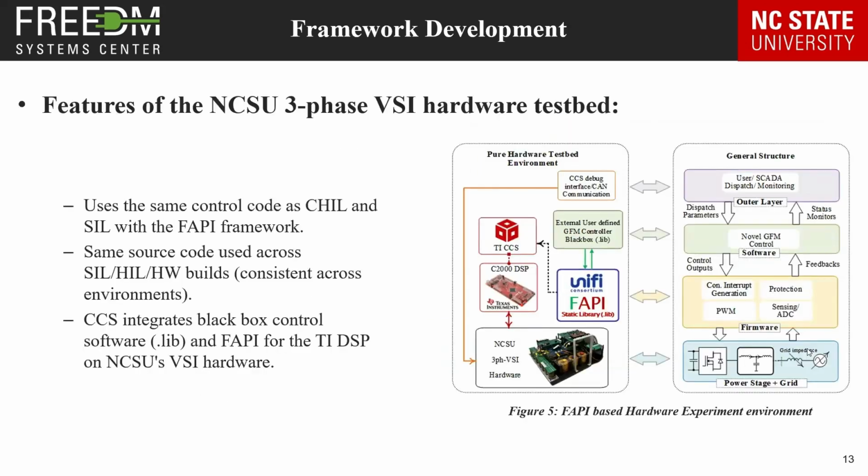The pure hardware testbed environment for the grid-forming controlled inverter adopts the same software control code as the HIL and SIL development environments when the FAPI framework is used. The difference in sensor types, as in the ADC for the HIL setup or the SDFM for the hardware, and the command and reference interface will be taken care of by the FAPI library. The external developer or user-defined GFM control software part will stay identical regardless of the development environment.